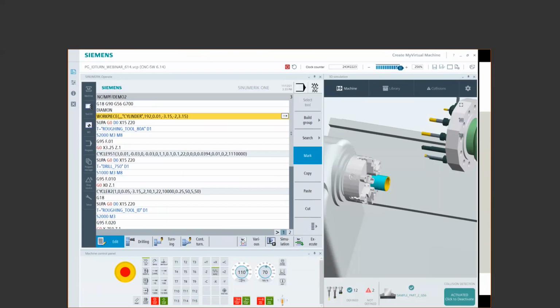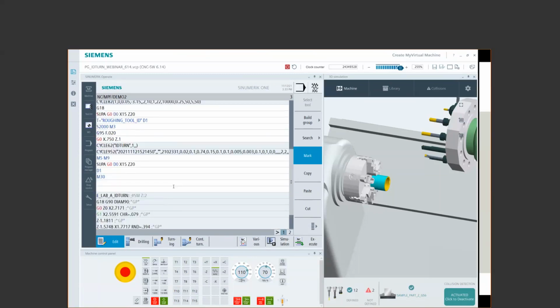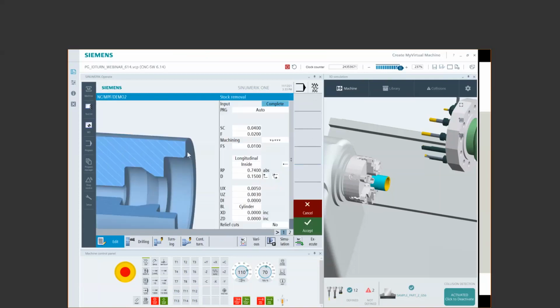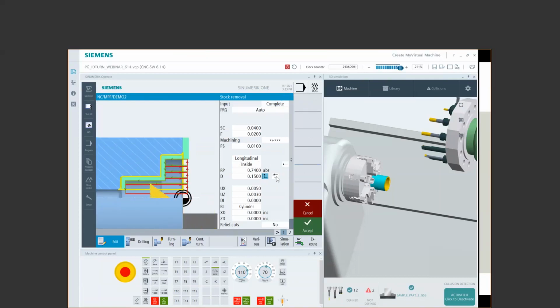That's a good question. So one of the things you can do, and I'm trying to fully get my head around the question, in the contour turning cycle, you can have some control over the retract based on these icons here. So the initial is going to take its first cut based on my starting location and my depth per pass, right? It's going to back off from there. But beyond that, it's going to back up the cut amount, but only if I have that at a full L. If you leave this as just a straight, it's going to just back up a predefined amount.